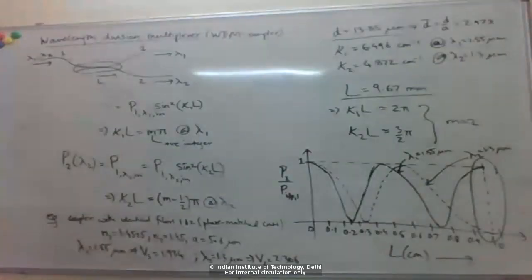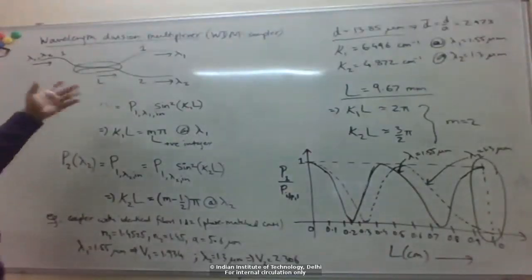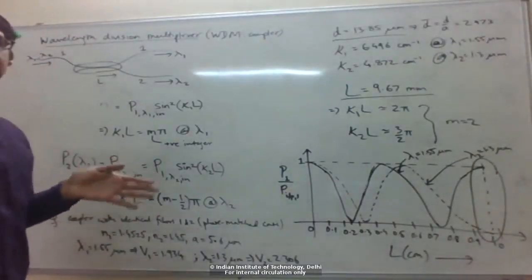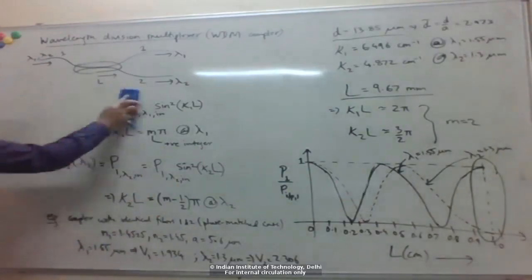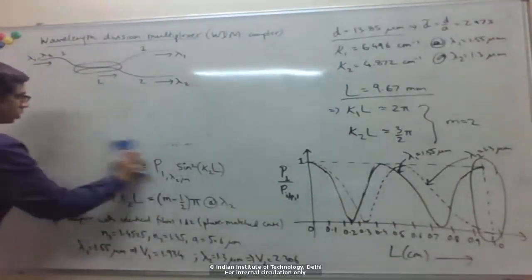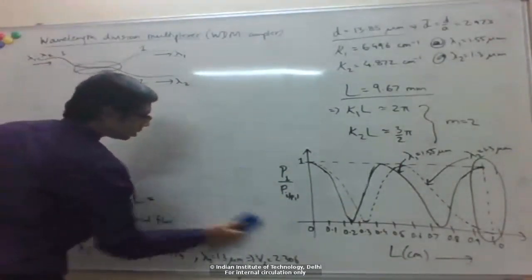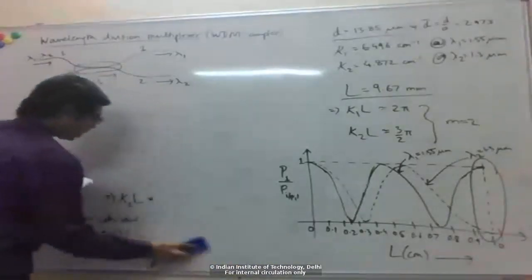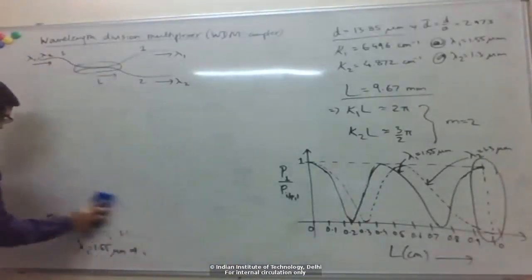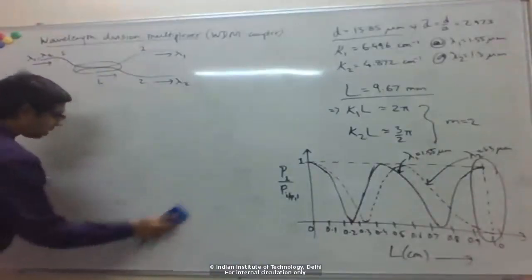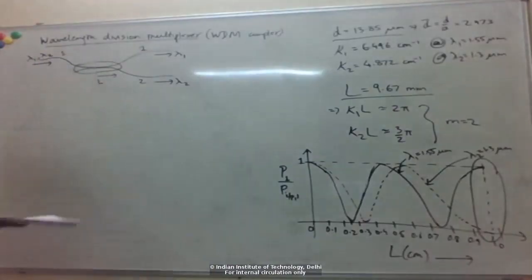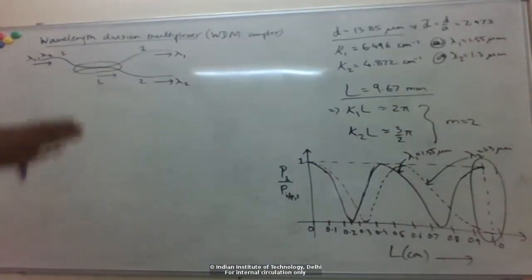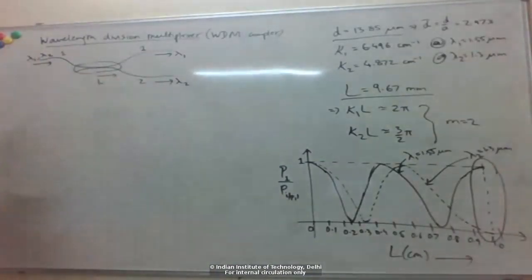So you can play these games and make the devices more wavelength insensitive or operate over a broader bandwidth. Nowadays you can get these WDM couplers operating over quite a wide bandwidth, like tens of nanometers around some specific wavelength.